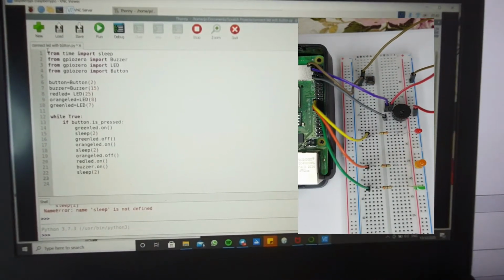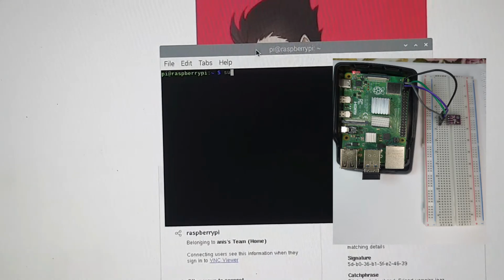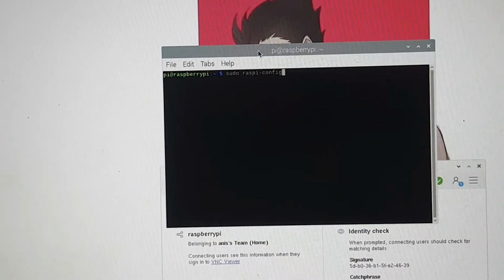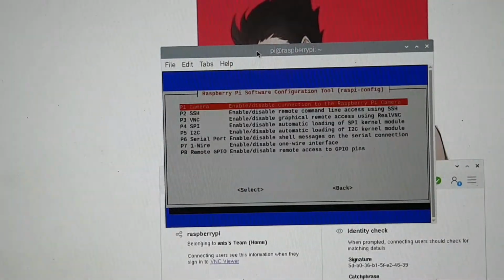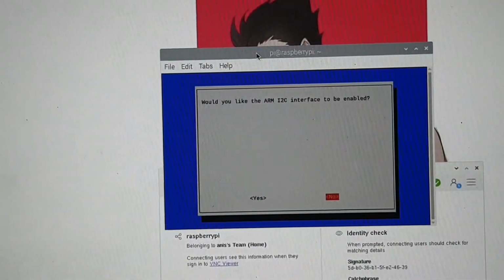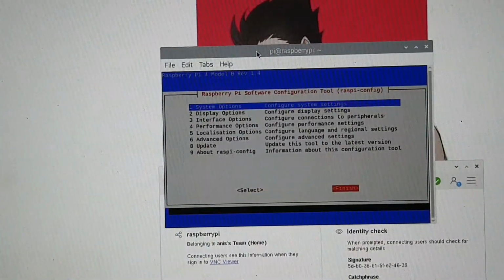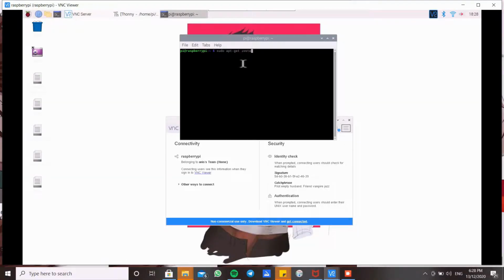To use the BME280 sensor, connect to the Pi's ground, 3.3V, SCL, and SDA pins. Enable the I2C kernel driver and increase the baud rate from 100 kHz to 400. Restart and add the Raspberry Pi user into the I2C group. Make sure the BME280 is communicating with the Pi properly, which can be done using the Pi's Linux terminal.